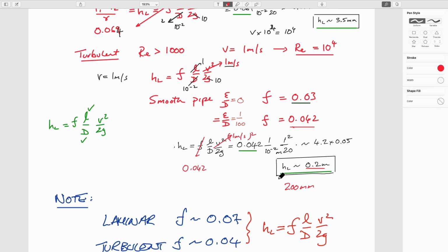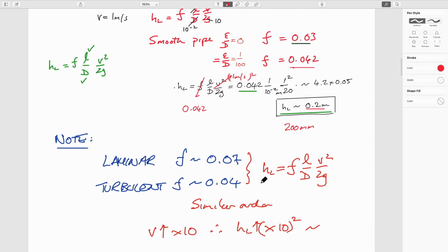So I guess the final point would be to make that this motive power can be provided by having your pipe, which is in the system like this, where you're going from upstream at some pressure which is the head loss between upstream and downstream, or the pressure at this point could be 0 atmospheric, and it could be 0 atmospheric here, and instead you could have a pump within the system which is supplying exactly this head loss to drive it along.